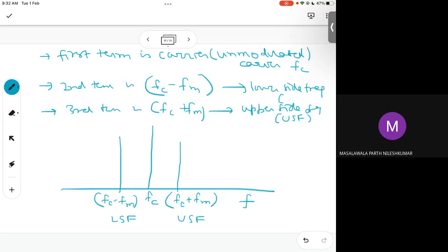So basically, my information, which was my message signal, will be contained in all the three frequencies, because that is my amplitude modulated wave. It is also contained in the carrier. It is also contained in the two side waves. Their amplitudes are nearly the same, so I'm putting it like that, but the carrier has a different amplitude, which is the original carrier amplitude. And this amplitude of the sidebands depends upon the modulation index.